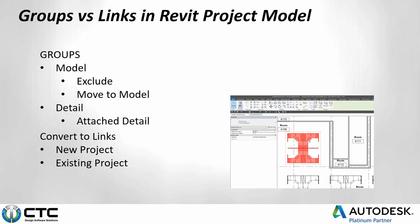group. And if you select both the model group and the detail group at the same time, or model elements and detail elements at the same time and create a group, it will create a detail group and a model group. And everywhere you place that model group, you will be able to attach the detail group to it later. And then if you don't want it, you can remove it from one instance of the group but keep it on another, but it's still there if you ever need to turn that on in any other view you want to see it in, that detail.